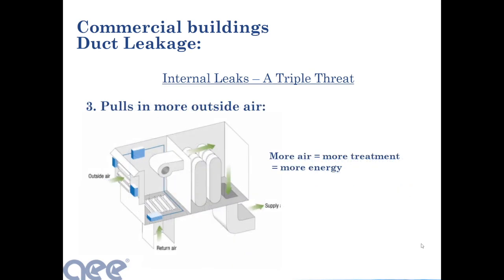And then the final problem that you've created in a commercial property whenever you have duct leakage is you're bringing in ventilation air. As you can see from the graphic, we're pulling in outside air. We need fresh air in the building to make sure of good indoor air quality. But the problem is if your fan is running more than you need, you're bringing in too much ventilation.